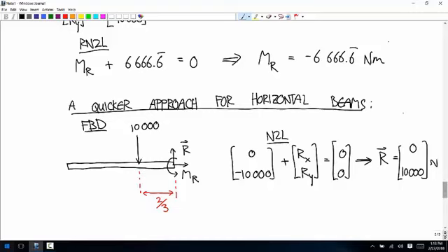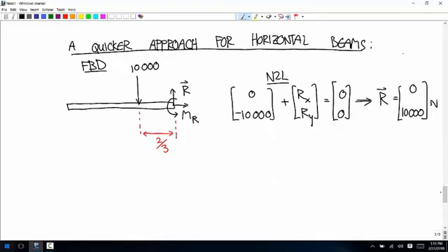Now we're going to do the moments. And in most problems, it's nice to write out that r-force-moment table because r vectors are sort of complicated. Notice that in a case where you have horizontal beams, nothing's complicated about those r vectors. Every r vector is just totally horizontal, and every r vector is totally perpendicular to the vertical components of the forces.